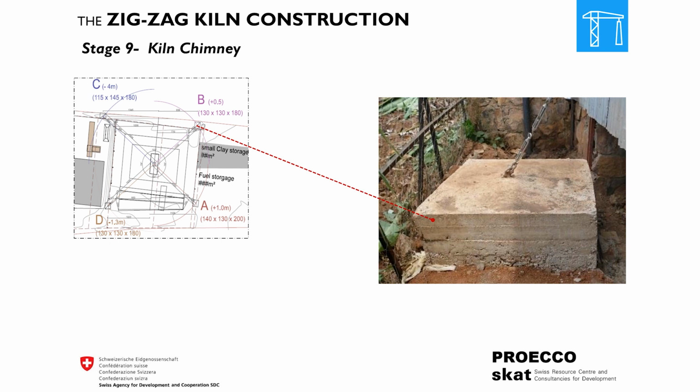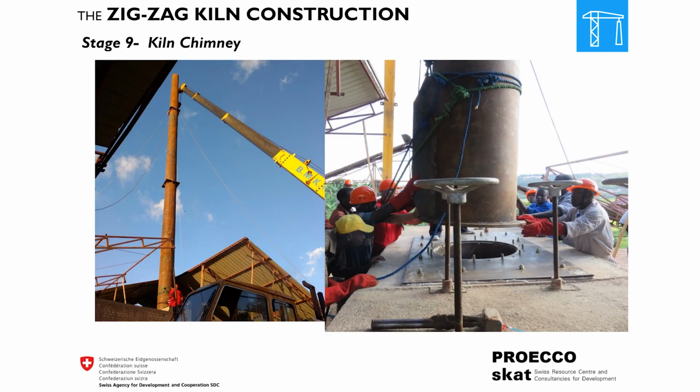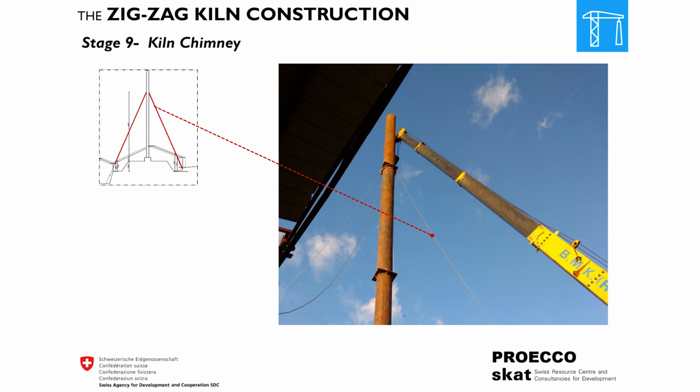The chimney is then elevated using heavy-duty equipment and fixed to the kiln top by means of anchor bolts concreted on the top of the firebox. A fireproof fiber mat is then pressed on the top of firebox floor control box to seal the gap between firebox and the chimney. The chimney is anchored and braced to the 4 concrete cubes by means of stainless steel guy cable.